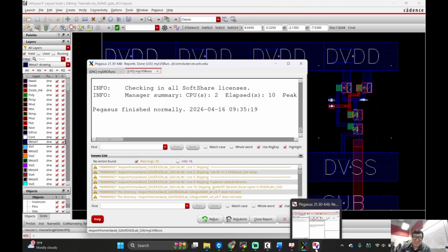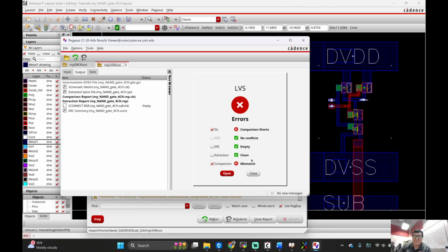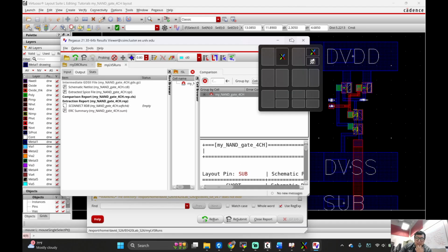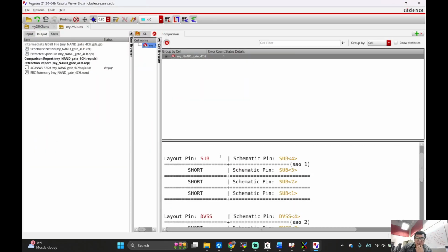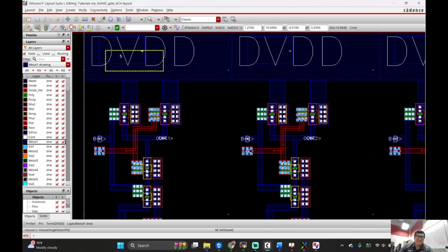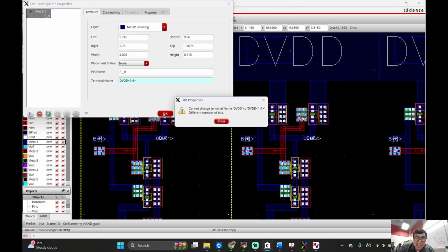All right. Where's my LVS? Here, it's right here. Let's see. Damn. Mismatch. All right. Let's see what happened. It says sub. You know what's going on? It wants this, 1 to 4. Cannot change different number of bits.